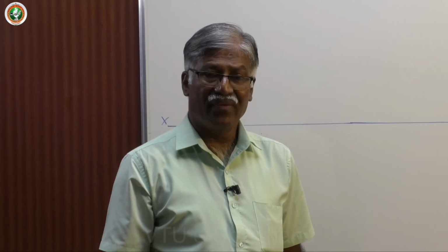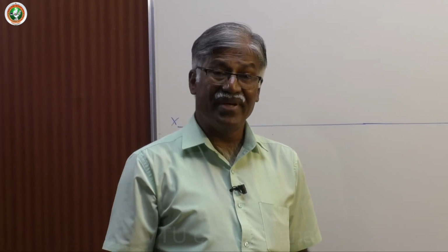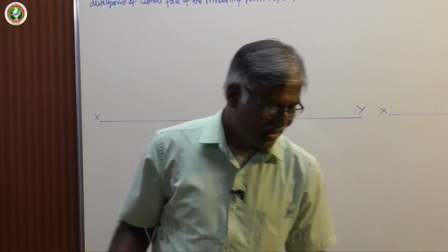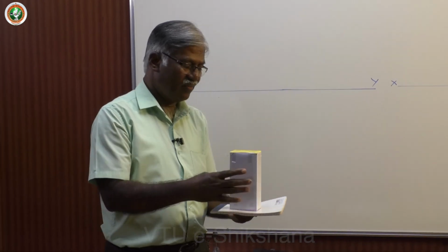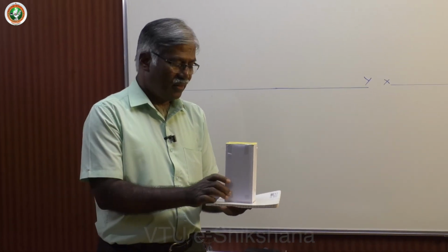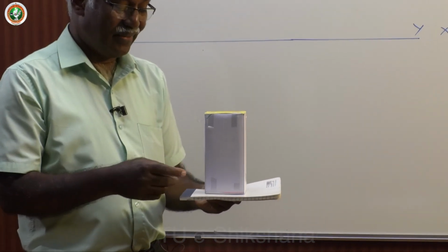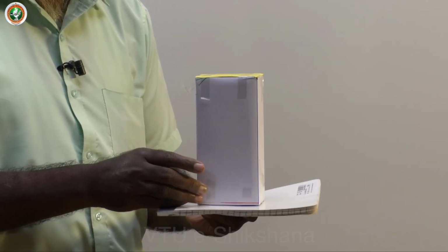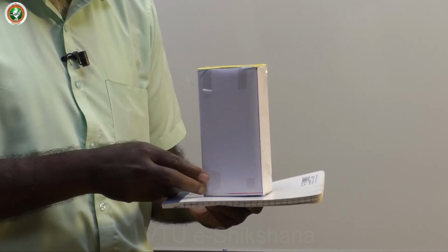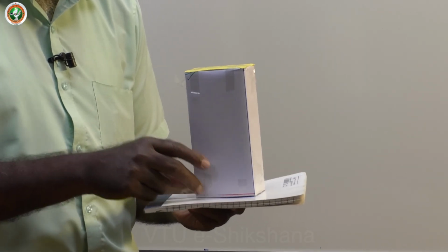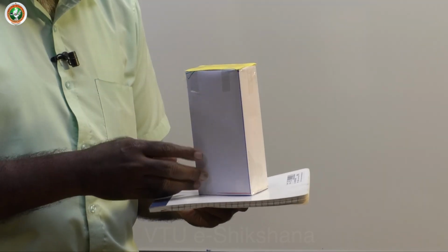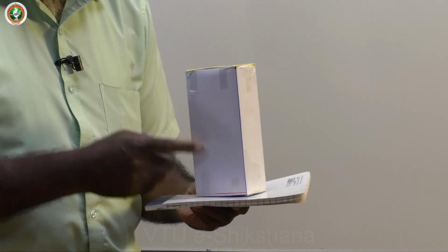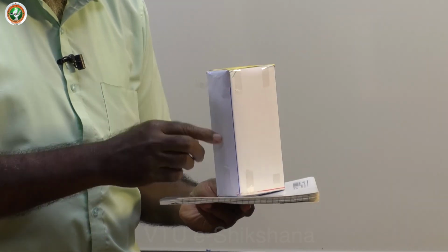For example, whenever you get a problem in development, the basic position is important. So, for example, we have the solid which is placed on HP. The questions will be like this: the base on HP is inclined at some degree, a base edge on HP is inclined some degree to VP. Say for example, the longer base edge or smaller base edge, or you will refer to the lateral face. In this case, the larger lateral face, larger rectangular face, or smaller rectangular face on ground.